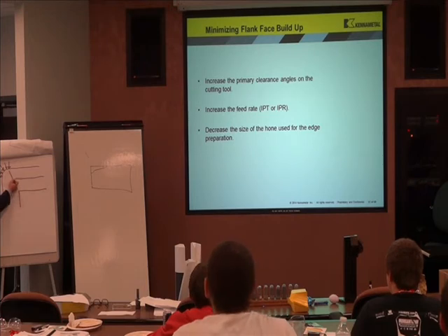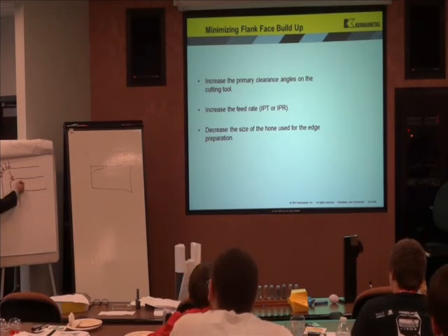Here, they would be going in this direction, again, into my string. Here, this whole thing is going to want to pop off. Just like that. That's why we put edge prep on inserts.